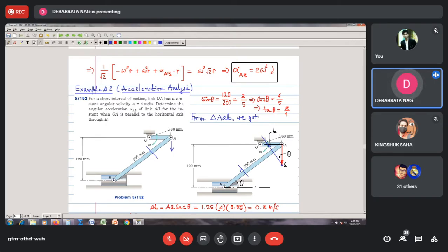Since the point B is only allowed to move along the horizontal direction, either this or that, the absolute velocity will be horizontal. So through pole A, I draw a horizontal line, and allow these two lines to intersect at point B, and we get this right-angled triangle. Now I solve this. This is one unknown, this is another unknown. So I solve for the unknown AB. This small AB is found like that. It is going to be 0.3 meter per second. Just apply your angles, simple geometry. I need not explain what geometry is applied here.